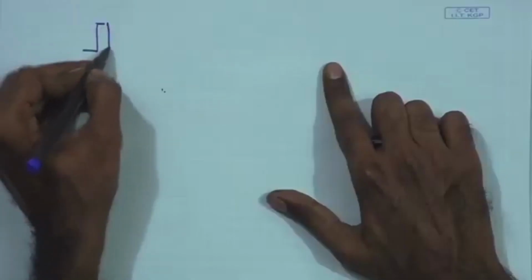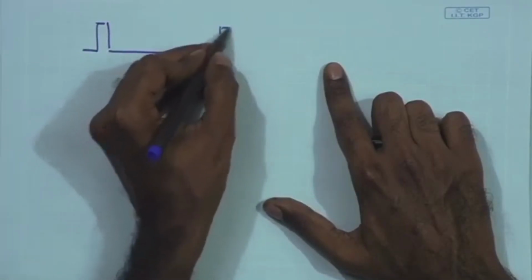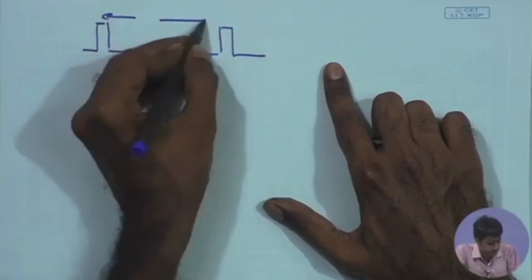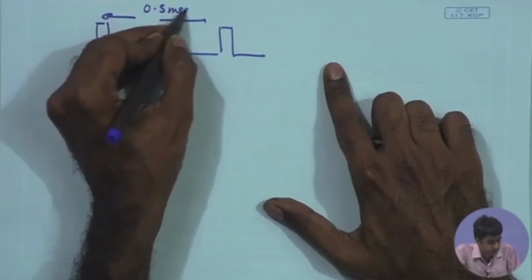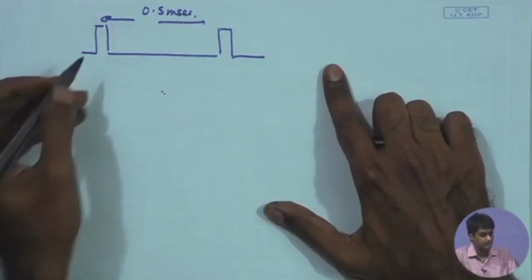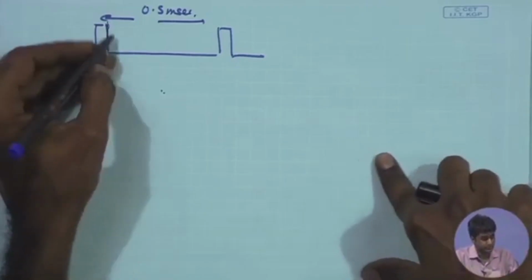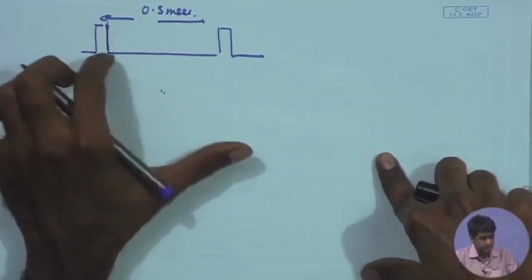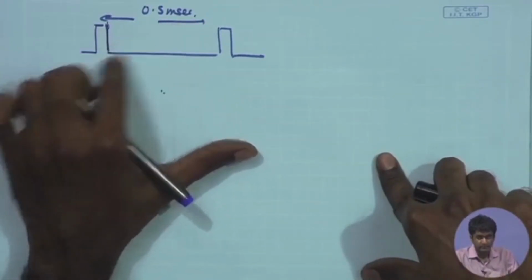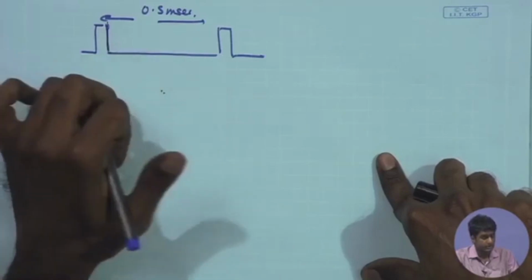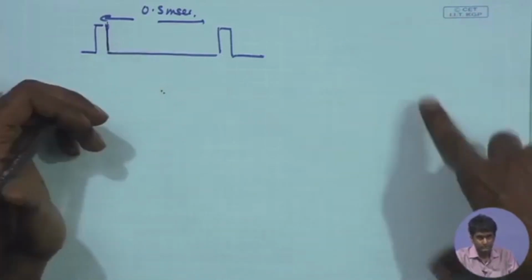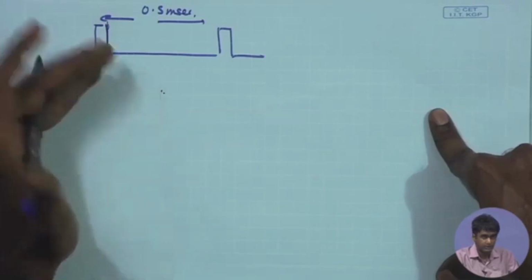If I look at the operation once again, the sampling duration Ts that I have chosen is around 0.5 millisecond in this example, and as I have said, the comparator is supposed to compare the ramping Vref with the sampled input signal. There are two important specs we need for the comparator: the gain and the bandwidth.